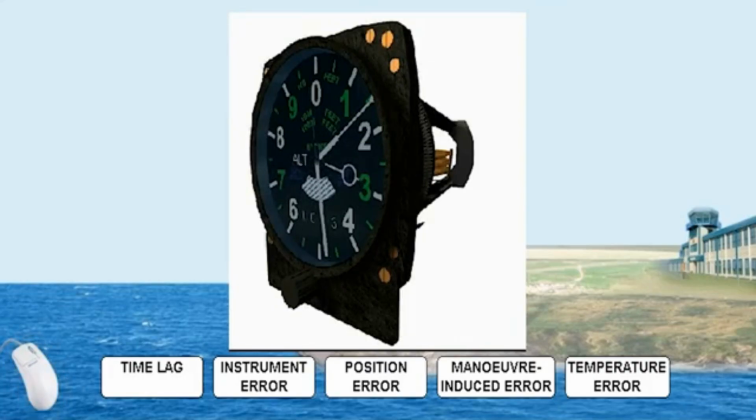Manufacturing imperfections, including friction in the linkage, cause errors throughout the operating range. The errors are kept as small as possible by adjustments within the instrument, and the calibration procedure ensures that they are within permitted tolerances. Residual errors may be listed on a correction card.